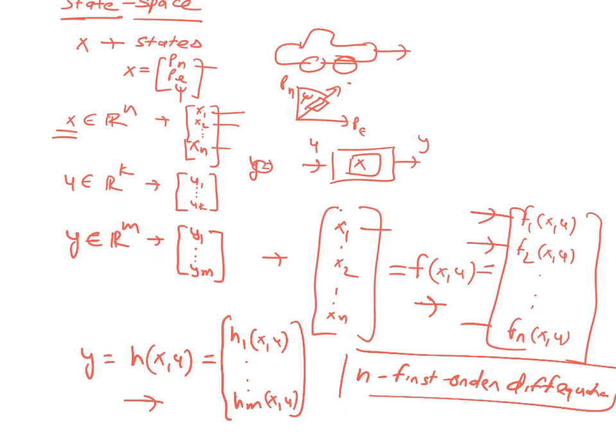This will apply generally to every problem that we'll be doing throughout the course. We will have a UAV which will have 12 states: pn, pe, pd, so the position, then velocity, then attitude, then the angular rates. So 12 states, we will need 12 equations of motion, 12 first order differential equations. Because once we get the differential equation for each first order, we can solve it and say how the states are varying with time. So that's the goal we have.